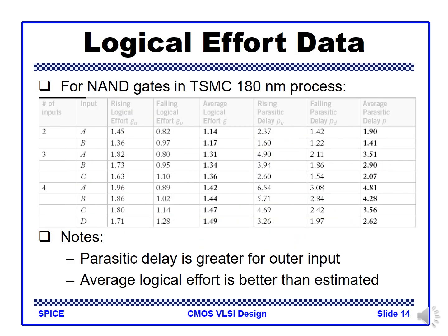This is the simulated NAND gate logical effort for the 2-input NAND gate, 3-input and 4-input NAND gate. We have different rise and fall logical effort for the different inputs. Those are different, because the circuit itself is not symmetric.